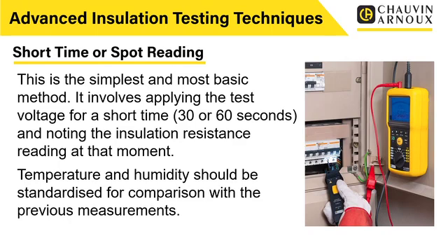So what that time is does depend on the insulation that you're using, the test voltage and the characteristics. But the key to this is you need to allow enough time for that insulation resistance reading to stabilize. If you're looking at the display and the insulation resistance reading is still changing, still going up or going down, you need to have a look at that and think, actually, I need to apply a bit more time to this.